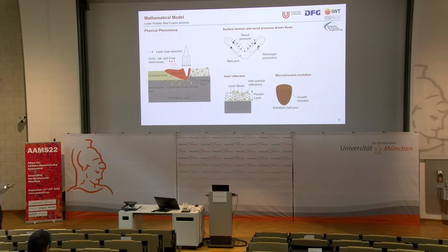Right now, in this current model, we have included only these physics. For microstructure evolution, we are currently working on a different phase-field model, which is basically a decoupling between this thermofluidic model and the phase-field model. There you can import data like temperature histories and other things from your thermofluidic model into the phase-field model, where you can actually see the evolution of grains or dendrites.